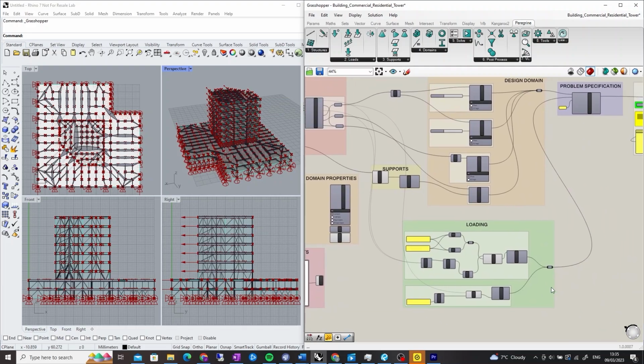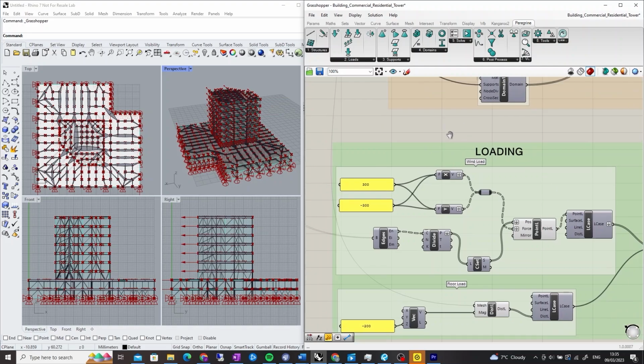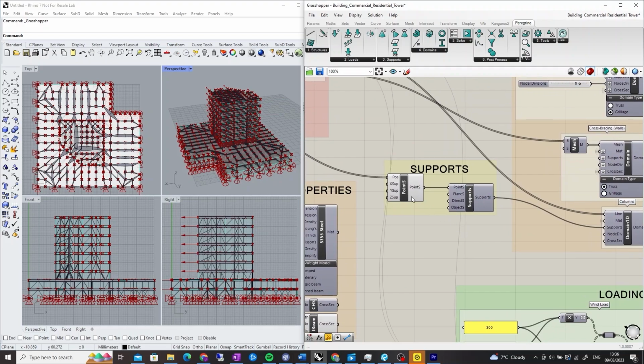2 load cases have been defined, one for the vertical loading and one for wind loading. Partial factors could be applied to the loads to create load combinations as load cases to match Eurocode guidance. Similar to the simple grillage problem shown earlier, supports are provided at the base of the lines used to define the columns.